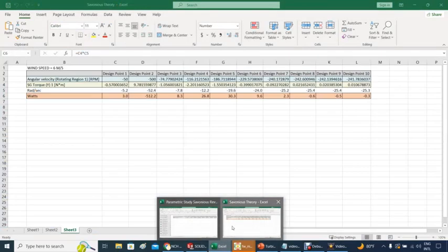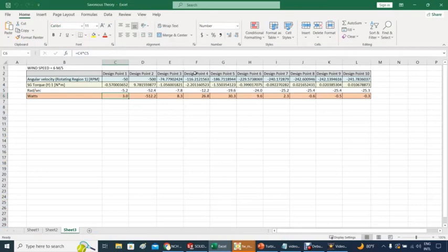It will look more like this. So that at 116 RPM you can extract a torque of about 2.2 for a total of 26. So you can have a range between 116 and 186, and that will give you about 30 watts. Yeah, can you get another number here? Yeah, definitely you can. Like for example, what will happen at 200? Remember, there's a correlation here. Yeah, the torque drops, but the RPM got increased, so it means that you can pull a little bit more energy, like in this case.